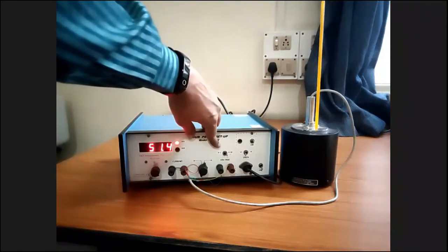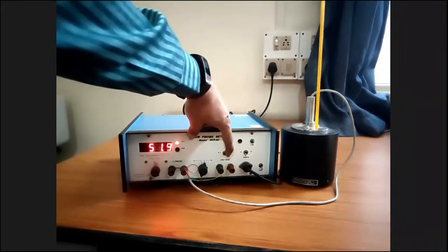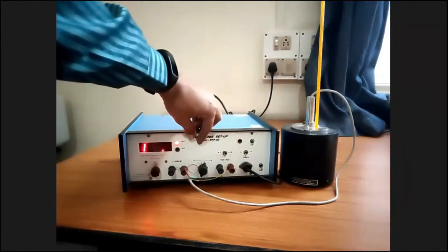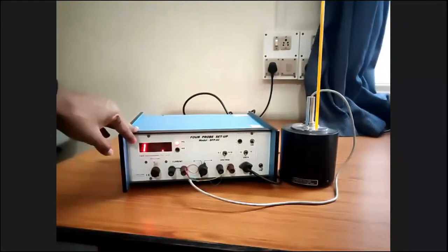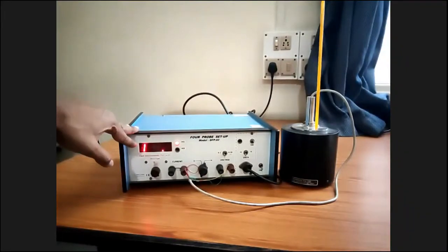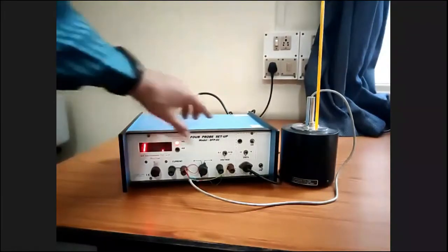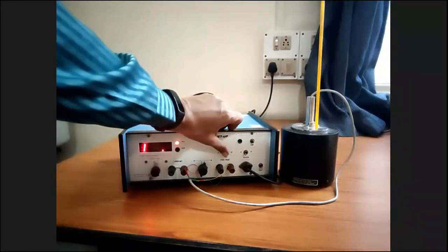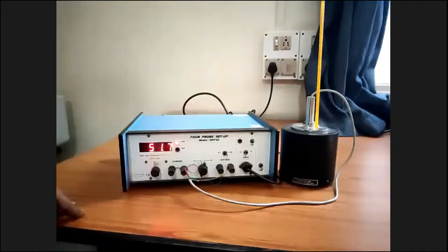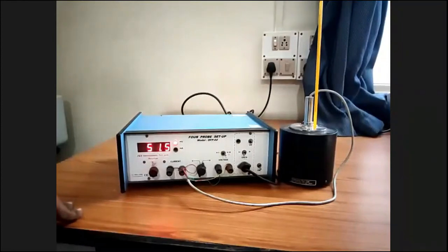This knob is on the left hand side. There is a times one setting. If I place this knob towards the times one side, the error symbol is showing in the meter. And if I turn this knob to the times 10 side, then you can see a particular voltage reading in the meter. Actually, if I turn this towards the times one side, this reading is outside the range of the voltmeter. That's why there is the error symbol.